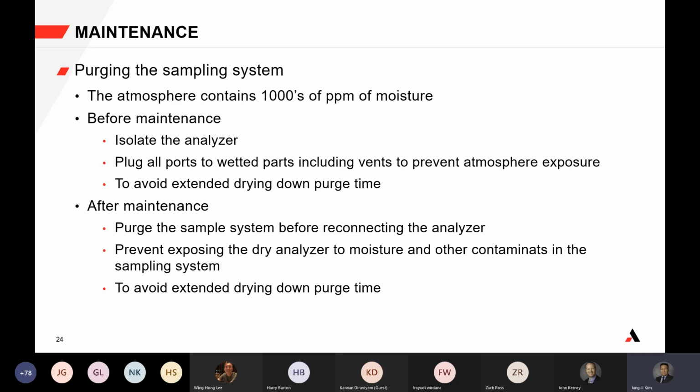Air separation plants that are next to or used for industrial, oil industry or any other industrial application, they don't remove moisture down to low levels. It all depends on what the customer is asking for. So I think plant nitrogen would at best be considered 5.9 purity gas. 5.9 purity means there is at least 10 ppm of impurities in the nitrogen.